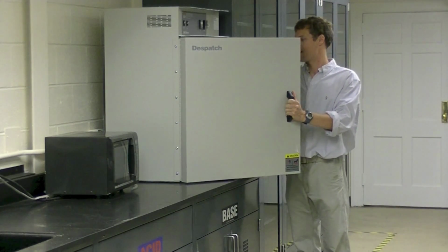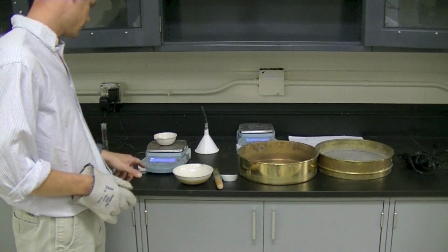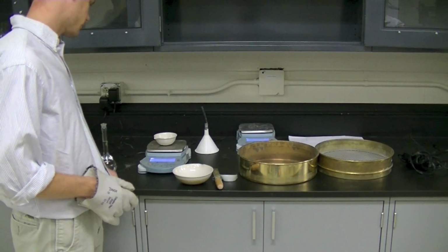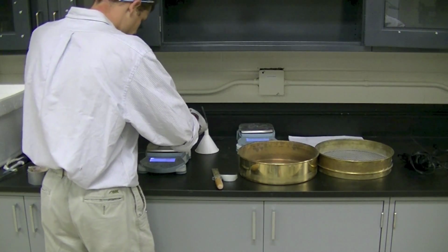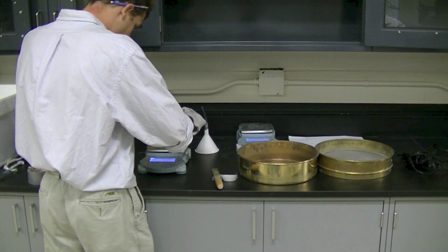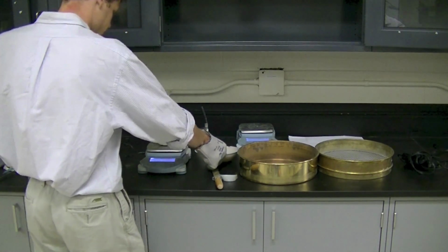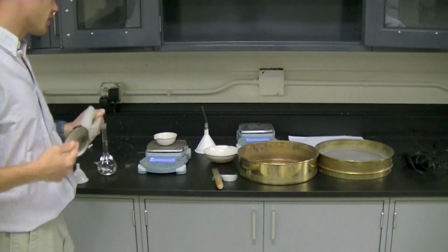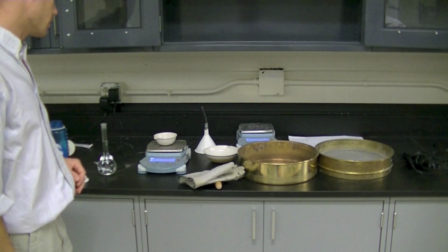Remove the oven-dry specimen from the oven. Table 1 of the standard designates recommended masses for test specimens, depending upon soil type and which pycnometer we are using. In our case, our soil is primarily clay, and the pycnometer we are using is 250 milliliters. Therefore, a 35-gram sample is recommended. 35 grams is weighed in a separate bowl or dish.